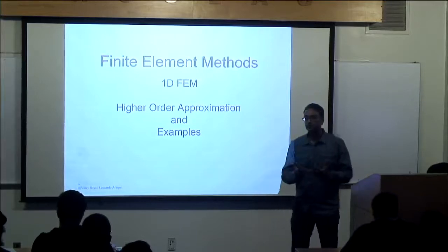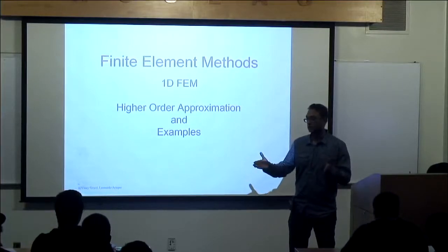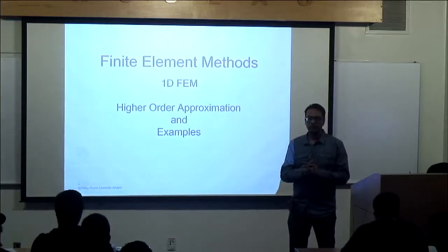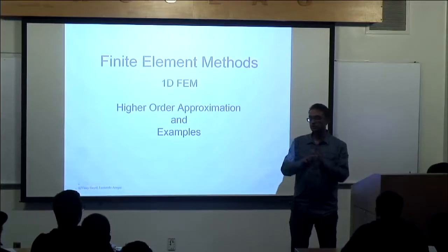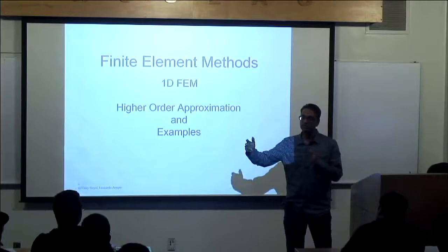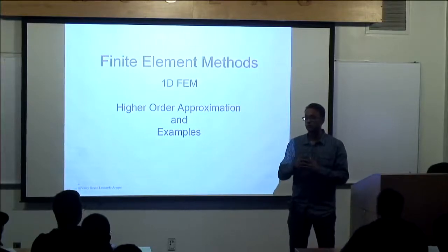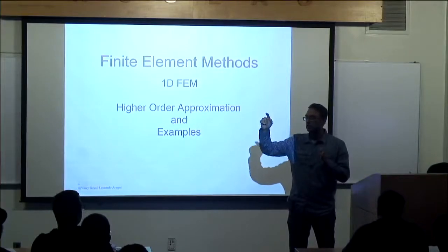And then after that, I showed you some examples where approximating the solution over the full domain may not be practical. Did everybody finish that one problem, the second problem of the last homework, where there was a beam on an elastic foundation? The solution should look like there's almost nothing happening at the center of that beam. But as you approach the edge, there's something called the boundary layer effect in structural mechanics, where things change very, very quickly, okay?